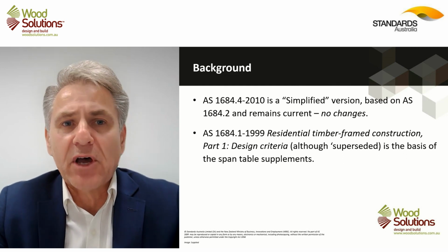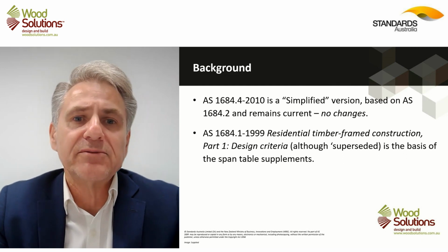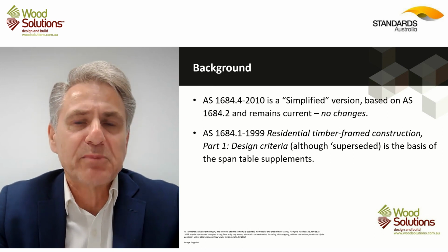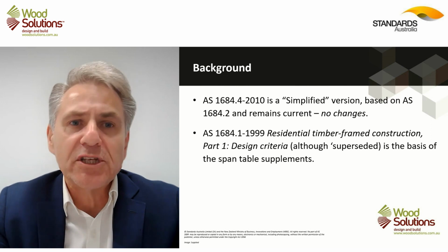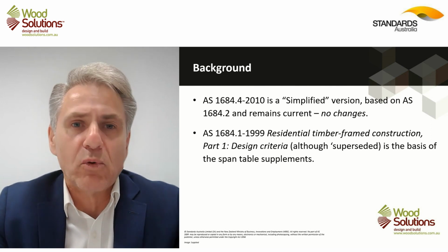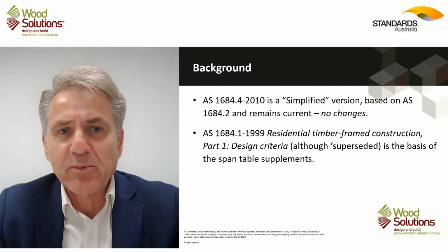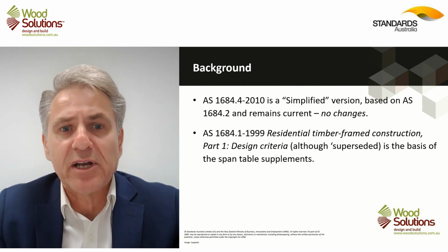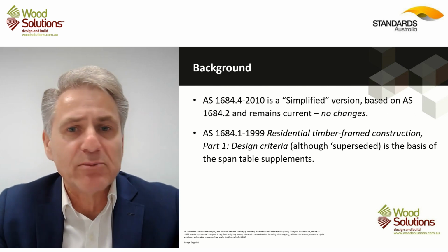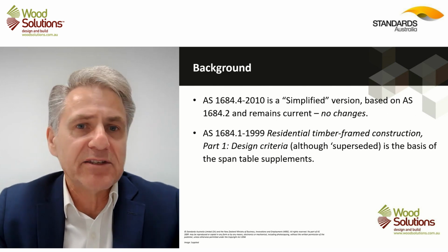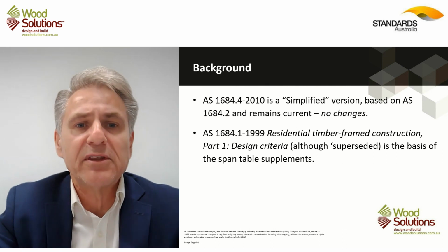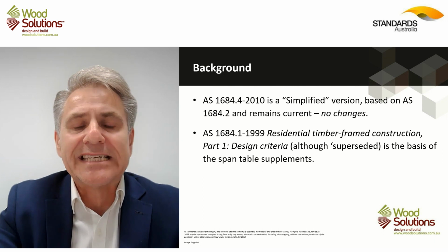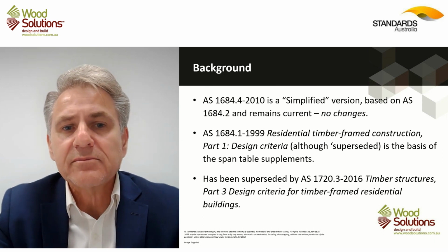One of the difficulties over the years is that since the span tables were originally developed, the basic knowledge has changed, or we've changed practices, but we've got long service life and performance out of our existing timber frame structures. So the span tables have currency and there's no reason to change them, even though they're based on this design criteria document that dates back to 1999.